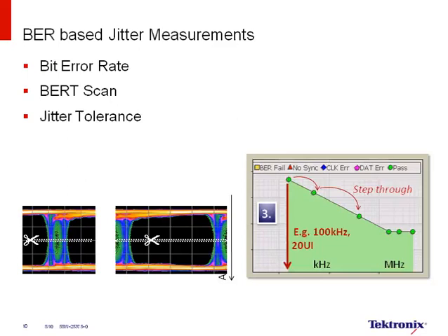It's also known as jitter tolerance, whereby for each SJ or PJ tone, you increase the SJ amplitude till the device fails. And once that's done, you move to the next tone, and again, you continue to increase that tone till the device fails. And you can just see a profile of how a receiver can deal with this. In many ways, you notice that it's the inverse of what's known as a jitter transfer function, which we'll talk about in the next few slides.